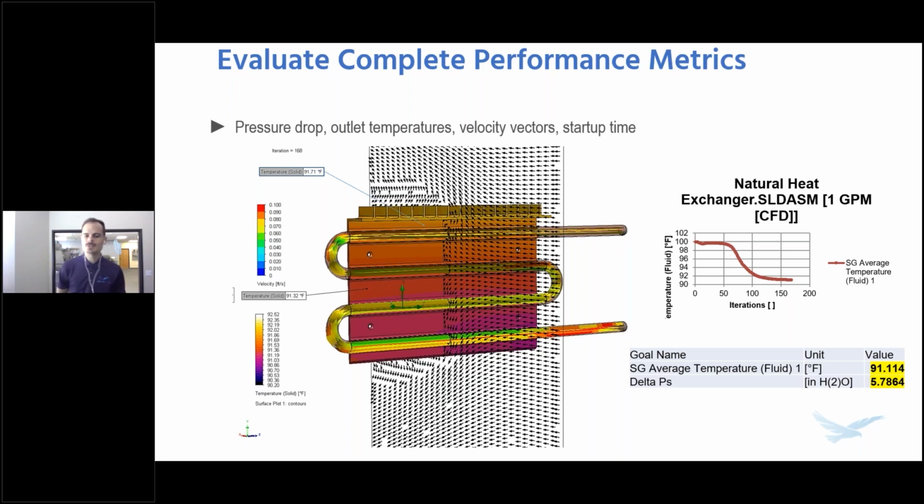Of course, that would let me specify the materials there, the copper waterline and the aluminum plate. And I'd also be able to figure out things like the transient behavior and really get the physical numbers, the physical data that I'm looking for, such as what's the actual temperature of the water at the outlet, and maybe what's the pressure drop in the system. Maybe that will help me size the pump that I'm trying to pick to run this thing. So of course, it goes beyond the qualitative result that FloXpress gives you in visual streamlines and gives you the real numbers you need to pick one design revision over the other.